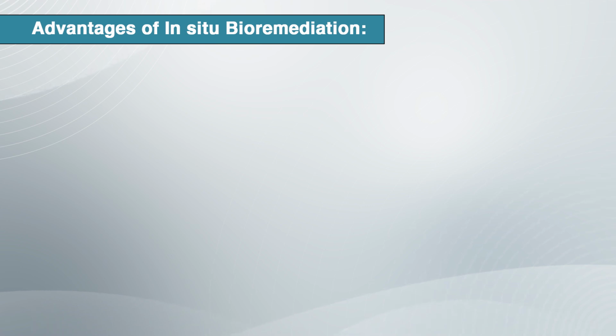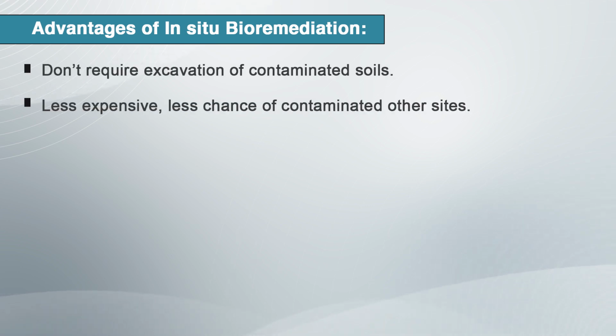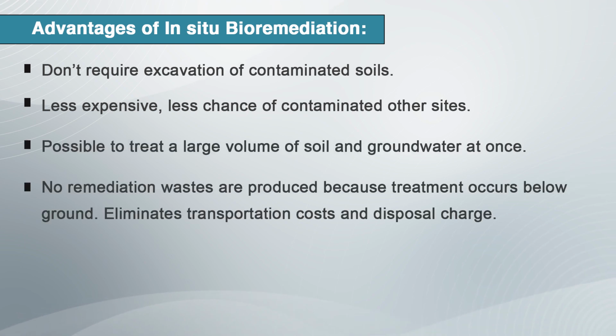Advantages of in situ bioremediation: it does not require excavation of contaminated soils. It is less expensive, with less chance of contaminating other sites. It is possible to treat a large volume of soil and groundwater at once, and no remediation waste is produced because treatment occurs below ground.